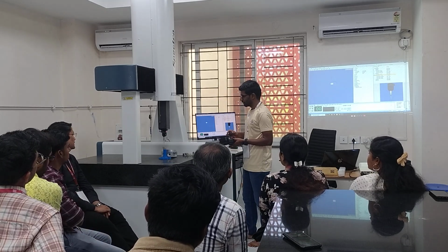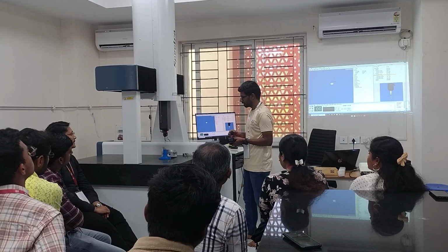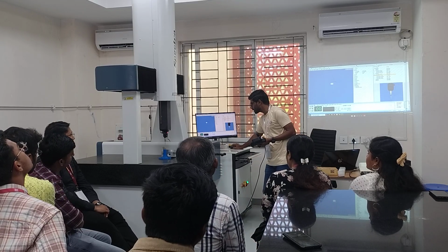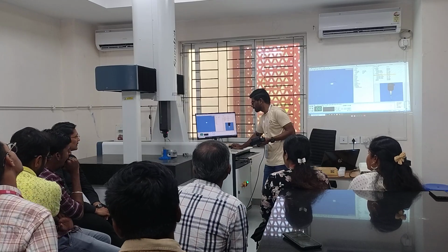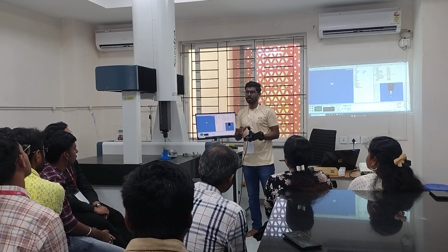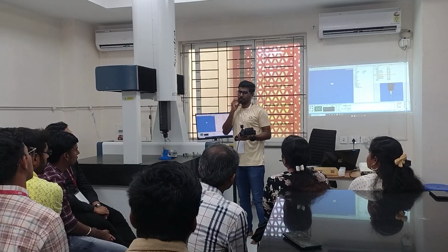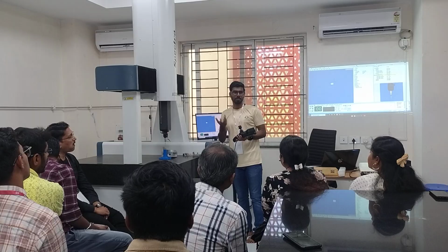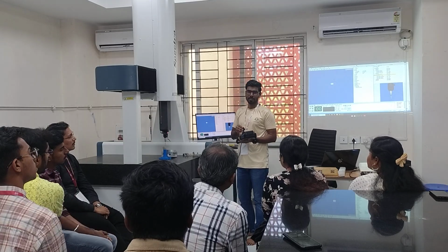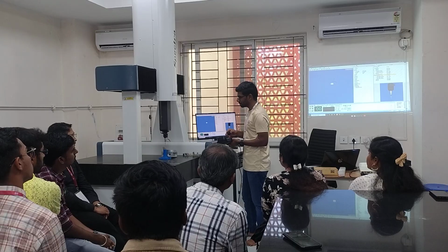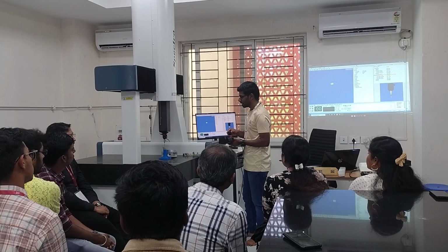Okay, let me do the circularity also so that we can compare. So plane is done. Now what do I have to measure? Let me measure circle. So I'll click on circle. For circle, how many points are required to trace a circle? 3. Minimum number of points? 3. Because 2 will give you just a line. 3 will give you a circle.